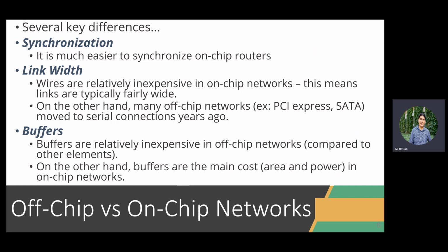And we gave the example of the AXI bus. We said one reason for this is you are already on chip, so the wires are very short, and hence you don't need a lot of synchronization. It's very cheap to have it. While if you go off chip, you better go serialized, right? So this is what we are writing here. In many off-chip networks, like PCIe, they are using serial communication, as we discussed already.